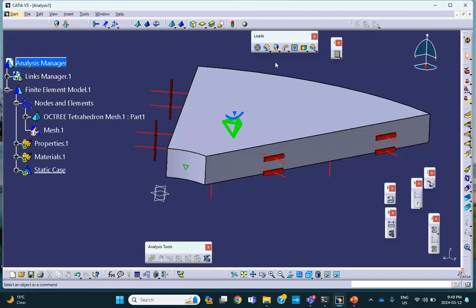But you know from your dynamics class that if an object goes around a circular path or around a curved path, there is always an acceleration, inward acceleration, which is called radial acceleration. So in fact, if you look at this thing, which has the kind of acceleration icon, if you expand it, you see that there's two things in there. One of them is linear acceleration. We have already handled that. This says rotational force, which means exactly what you want.